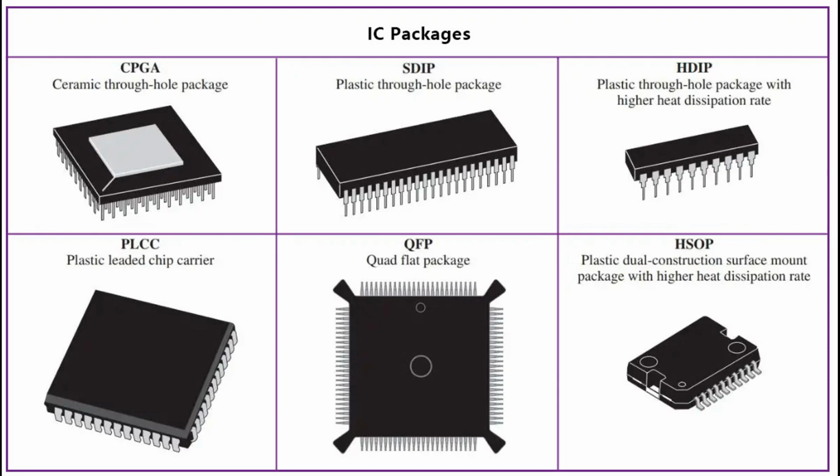6. Dynamic voltage scaling, DVS, and frequency scaling, DFS. Function: adjusts the operating voltage and frequency of a processor based on the workload. Reduces power consumption during periods of low activity. IC type: power management units integrated into processors or dedicated ICs for dynamic voltage and frequency scaling.